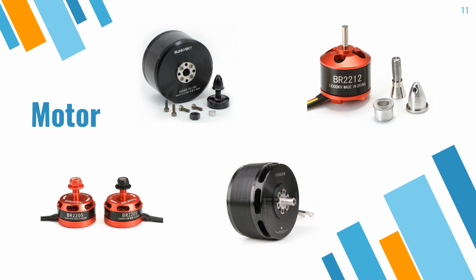Let's look at one more example. The other black motor in the bottom, this is actually the U15XXL, is capable of producing 100 kilograms of thrust, so this is really a heavy duty motor. It only has a kV of 25, so this means that this motor is more efficient than the Sunny Sky and way more efficient than the BR2212, but it isn't capable of rotating that fast.